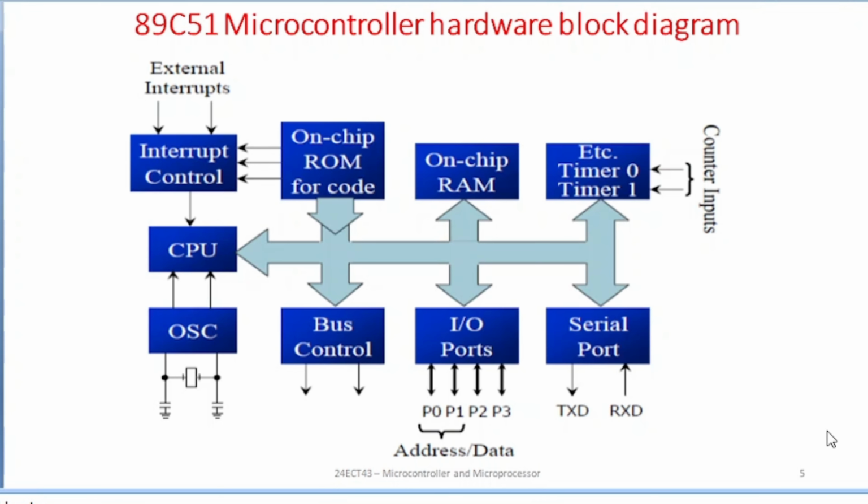Other important portions include 8-bit and 16-bit registers and 8-bit memory locations. It has some amount of data RAM built into the device for internal processing. This area is used for stack operation and temporary storage of data. 8051 is supported with on-chip peripheral functions like I/O ports, timers, counters, and serial operations.